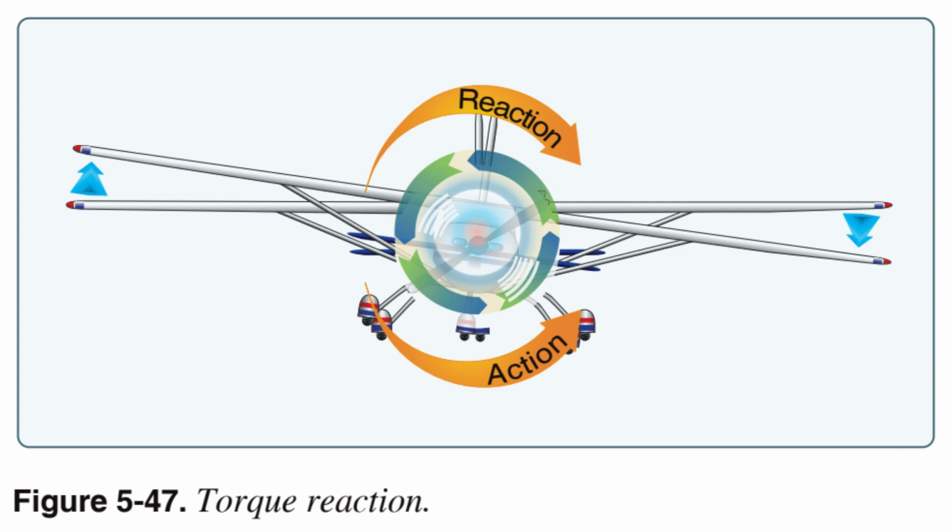When the aircraft is airborne, this force is acting around the longitudinal axis, tending to make the aircraft roll. To compensate for roll tendency, some of the older aircraft are rigged in a manner to create more lift on the wing that is being forced downward. The more modern aircraft are designed with the engine offset to counteract this effect of torque.